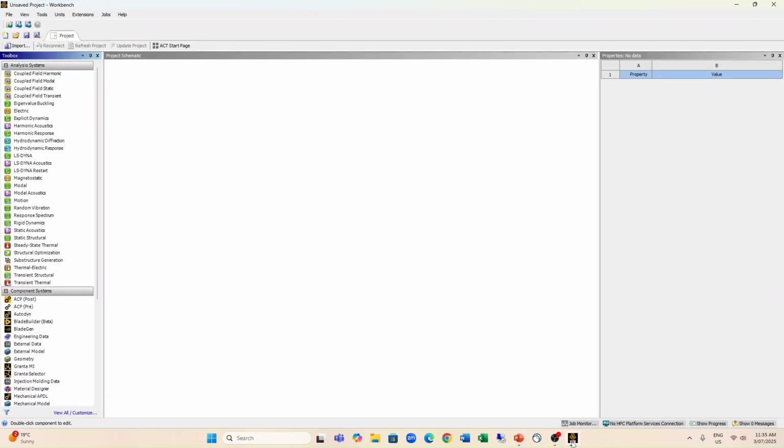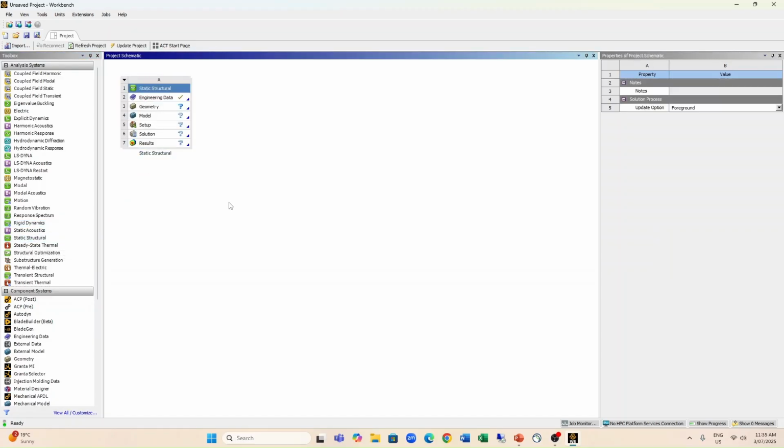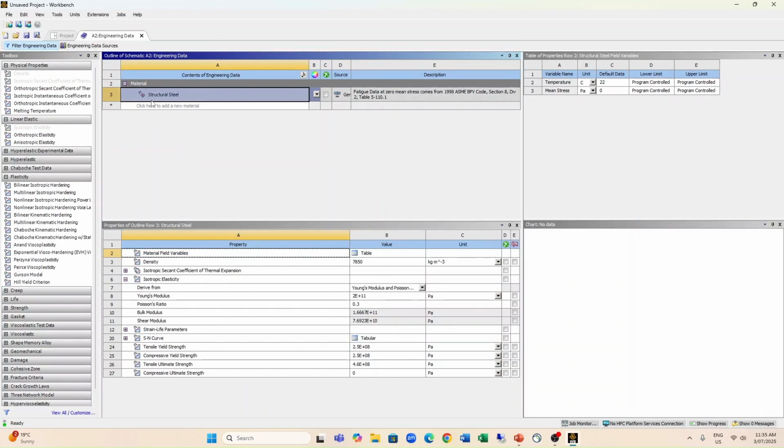In this video, I'm going to talk about how to create materials and material properties in Ansys Workbench. First, we are going to create static structural analysis. In order to define material properties and create new materials, we need to go to engineering data.